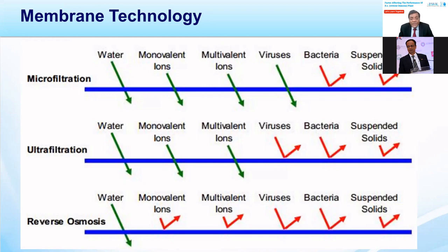molecular weight cutoff size. That is why all the membrane manufacturers normally test the membrane on the rejection of sodium chloride, because all other molecule combinations present in the raw water are bigger than sodium chloride. The membrane data sheet will make it clear. They mention that our membrane rejects 99.5, 99.6, or 99.7% sodium chloride. That is how they test the membranes for our application specially.